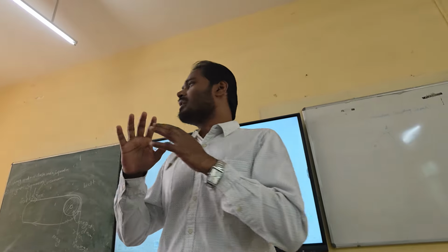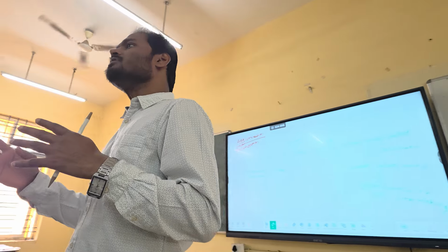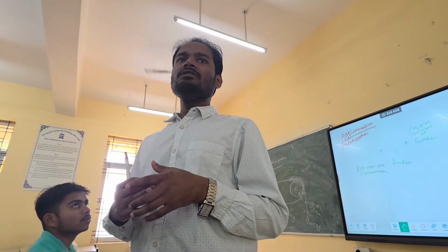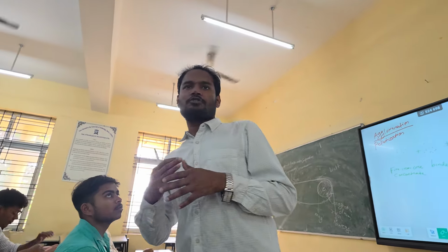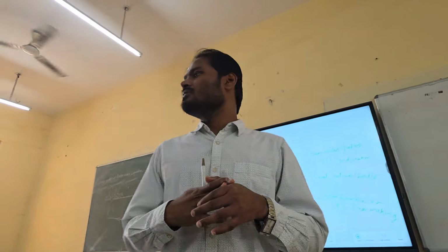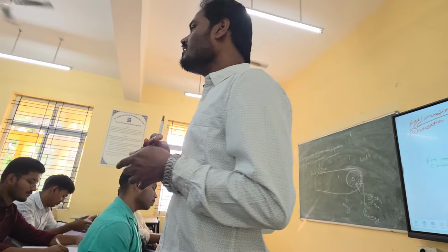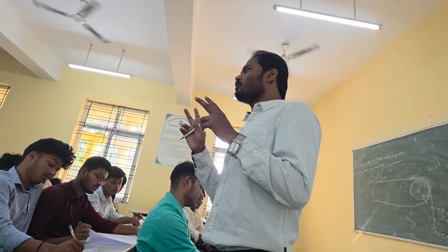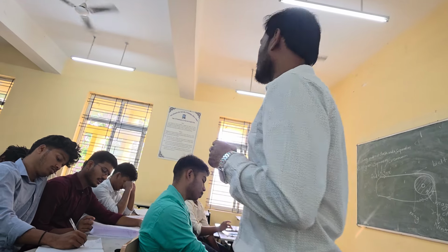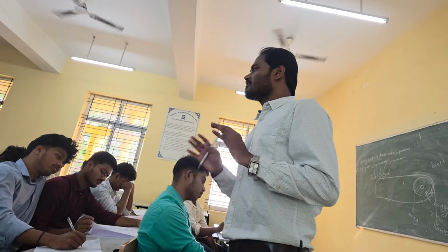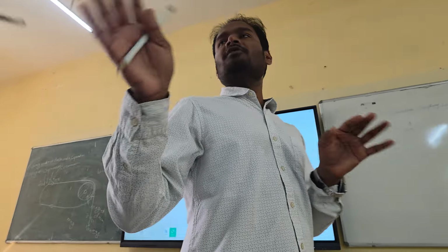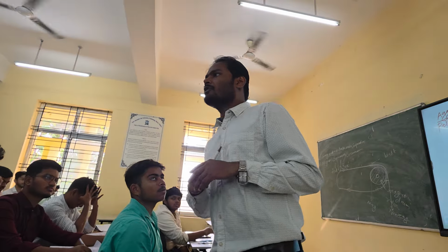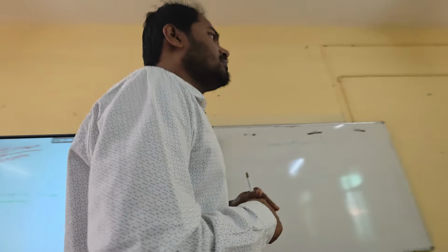And I told you there are many different techniques of agglomeration. If you remember, one is sintering, one is pelletization, one is extrusion, vacuum extrusion, others are briquetting and nodulizing, right? Apart from all these, the two important agglomeration techniques are sintering and pelletization. Sintering we have already discussed, right? And definitely when you go for your internship, you will see that machine, the Dwight-Lloyd sintering machine, how they are doing sintering there.